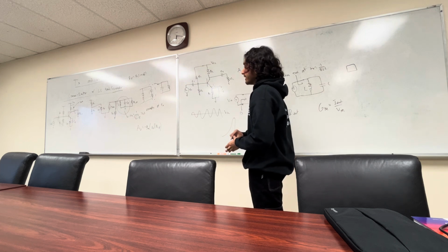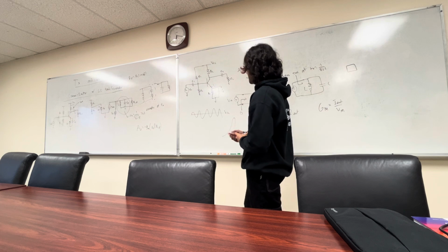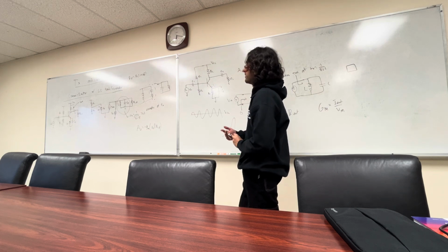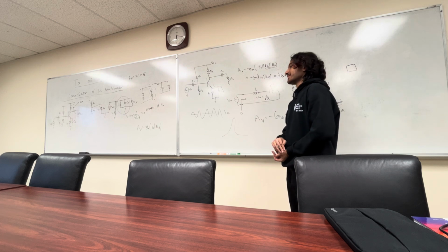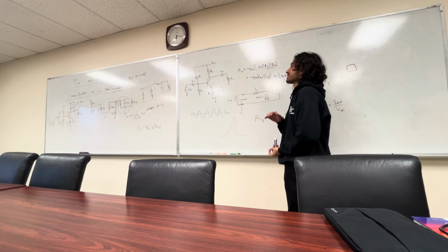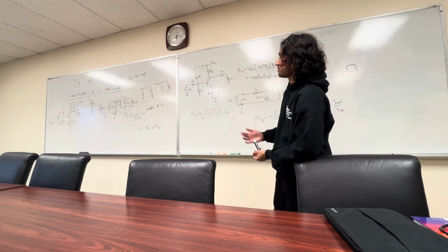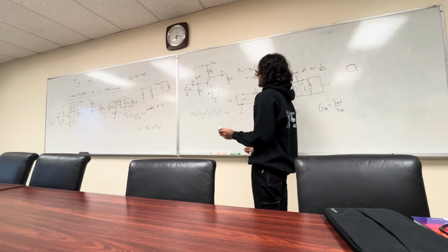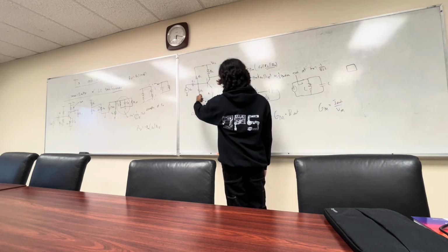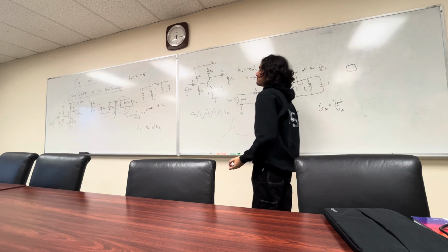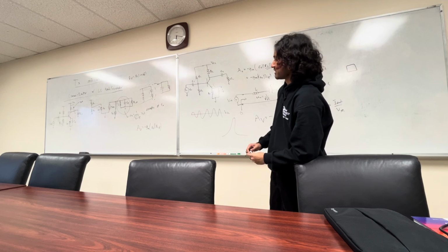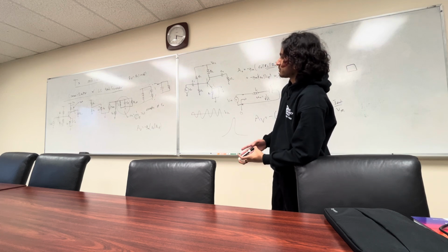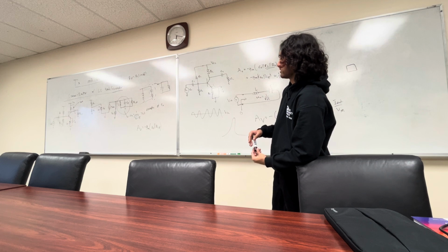And this touches on what I was just saying: when we make amplifiers, it's very easy to accidentally make an oscillator. You may think that's kind of weird at first because, okay, for an oscillator we talked about before, we have a Colpitts oscillator, where we have some feedback from here going back into our input, right? But do we see any feedback there? You can argue that RE and CE is a type of feedback, which it is, but that will never cause oscillation here.